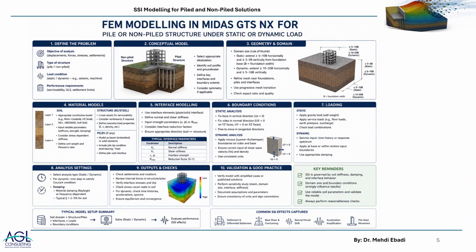Then we go to the type of analysis, which in general, for many projects, we only use nonlinear static analysis because we are talking about Europe, and in Europe, regardless of some countries, the earthquake is not the governing parameter.